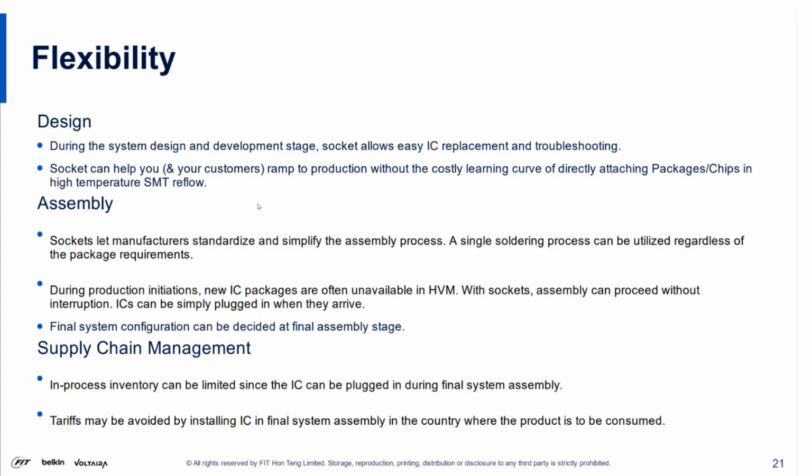During production initiations, new IC packages are often unavailable until HVM. With sockets, the assembly can proceed without interruptions. IC can be simply plugged in when they arrive. So the advantage of socketing something is that you can do your system level board design, system design quarters before the chip customer provides devices, rather than having to wait for that chip.